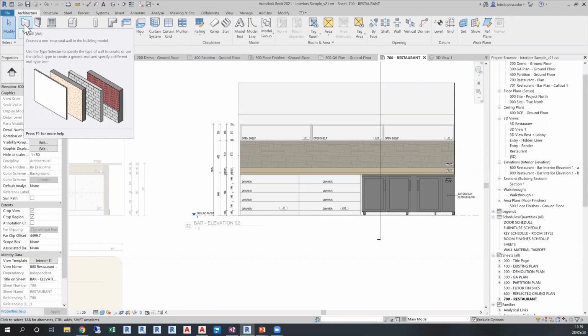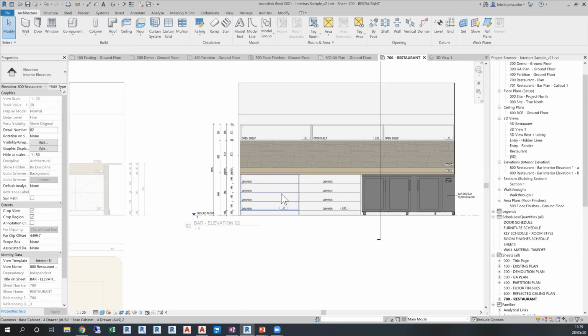If you have a good template with those developed, the loadable families, which are the furniture, we suggest to load them as you need within a project because of their impact on size. If you have a lot of families and your library is massive, that will increase the size of your template so much, for users who may use just certain families. So loadable families are always recommended to be within a library, and then you load as you need. If it's something that you use all the time, like maybe certain caseworks, definitely you can have those in a project.